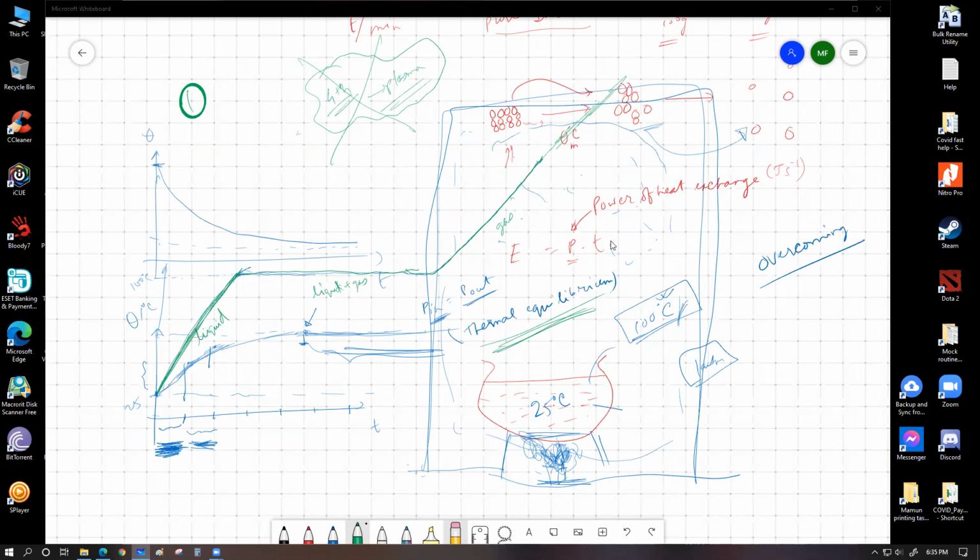Okay. So this is the important part that we have got from this information: we have to supply heat, and as long as the temperature increases, that means a single state. When the temperature becomes constant, where that constant temperature or the horizontal segment of the graph happens is the transition temperature, the state change temperature. This would mean state change, where we have liquid plus gas. It's a mixture of liquid and gas. And once all the liquid is boiled to gas, only then will the temperature start to rise up to this point. So that's the basic idea for this discussion.